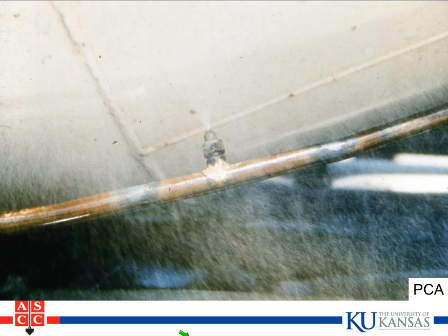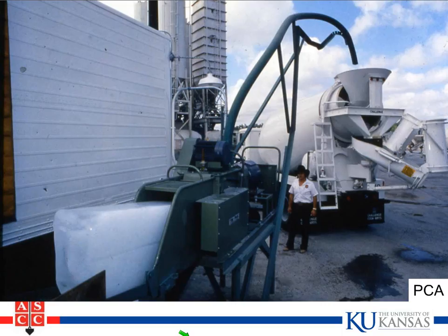Another thing, we like to start off with cooler concrete to begin with, because the cooler the concrete starts, whatever the environmental conditions, the less total heat it generates. It reacts more slowly, which is good, and the total heat that it generates is reduced. So this is an example where they're cooling the outside of a drum of a ready-mix truck. Here they're putting chipped ice in the concrete and replacing part of the mix water with the ice.